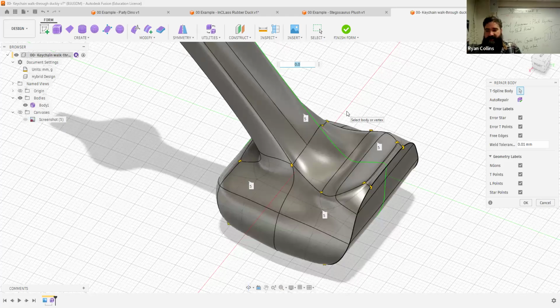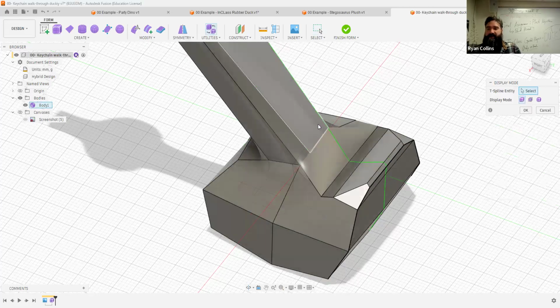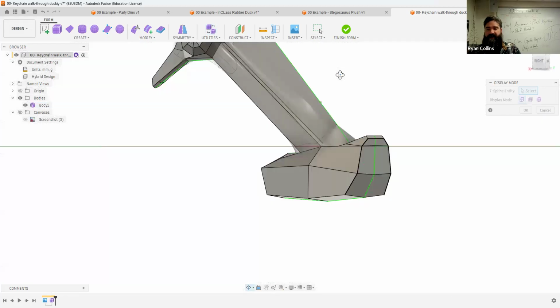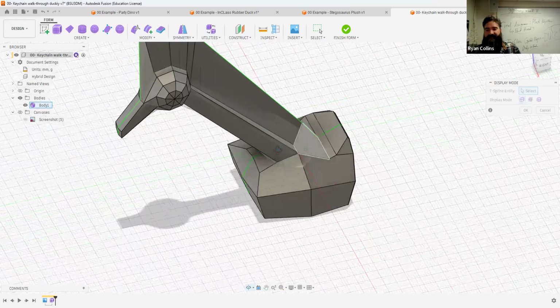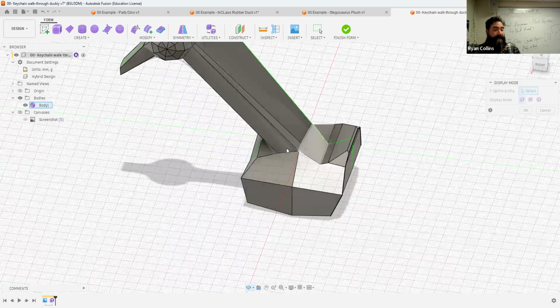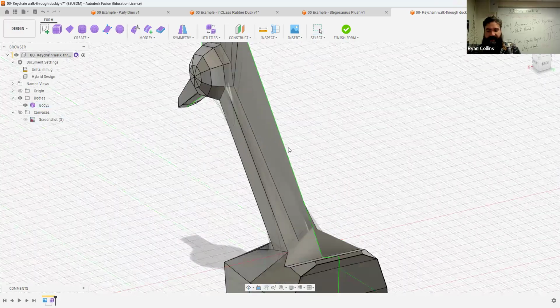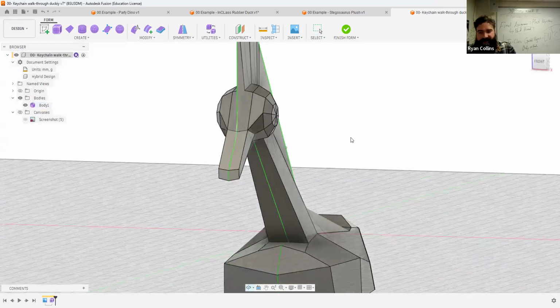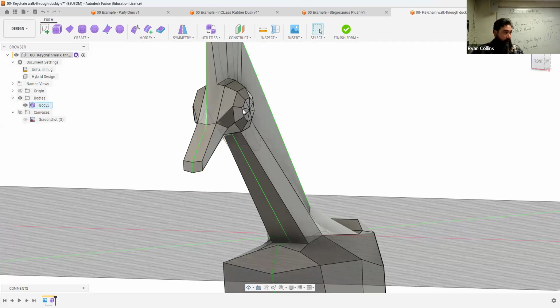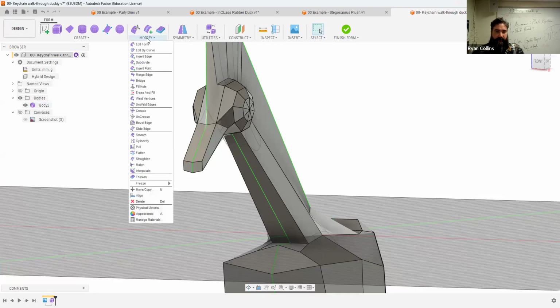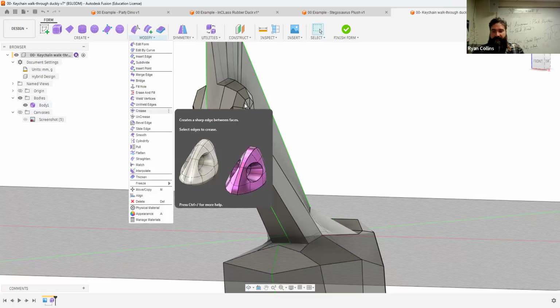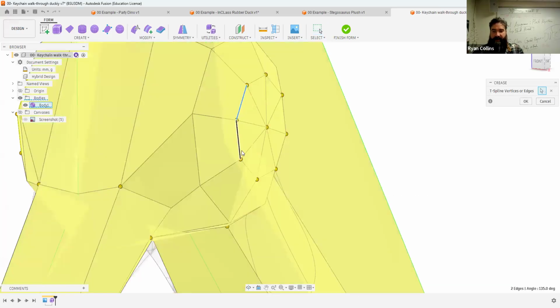And the easiest way to see it is switching display modes to box mode, and you can usually see crossed out areas or self-intersecting areas, things like that, a little more clearly. You can manipulate this in box mode. I can continue to play with this with the edit tools, edit form, all of that in box mode. Things like if I wanted to turn the eyes into more actual eyeballs, I could leave it in box mode and maybe use the crease tool. If I go around and select all of these edge lines here, now it's not going to display it because I'm in box mode.